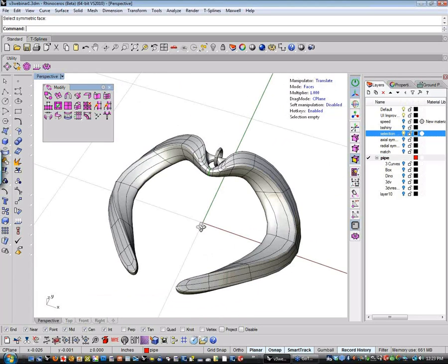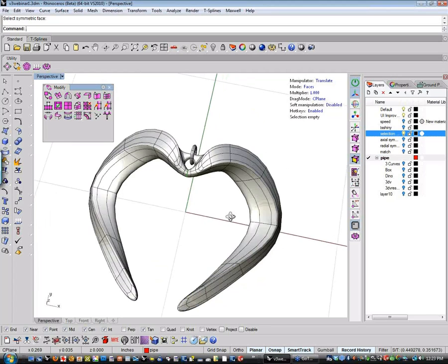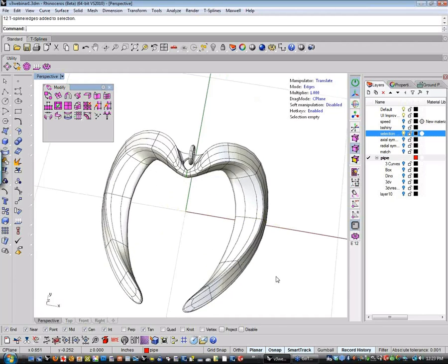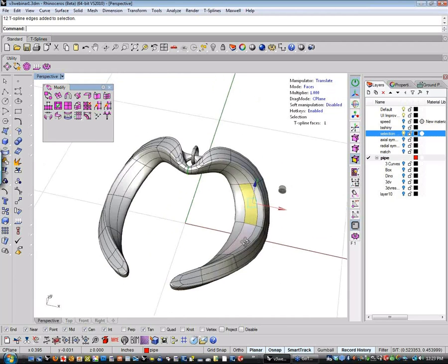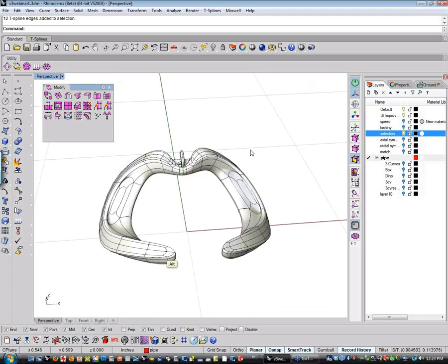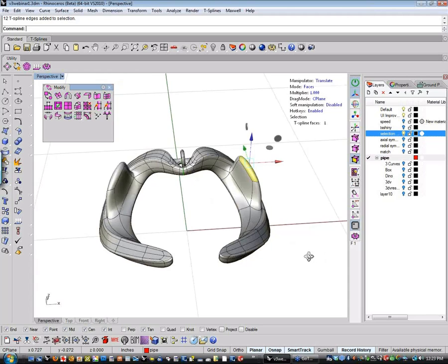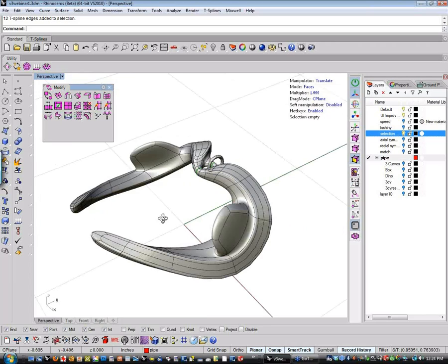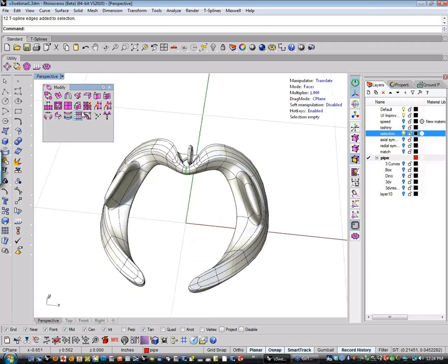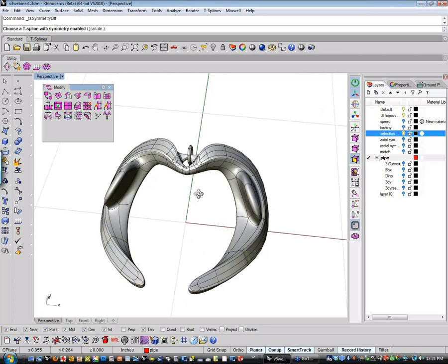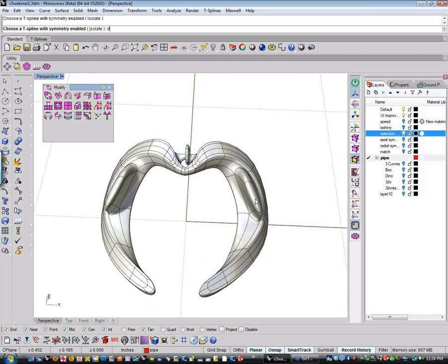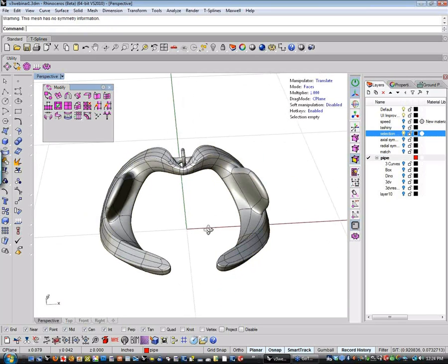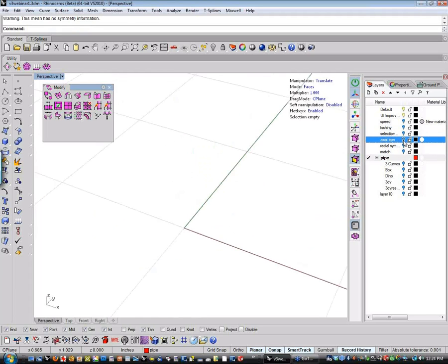But so that's really cool, and once this is activated, obviously you can come in here and pick any of this stuff and move it around, and it works symmetrically. It even works if you're extruding stuff. So if I put an extrusion in here, you'll notice that it extrudes it symmetrically across based on that once it's active. To get rid of it, all you do is right-click on this, pick this, and right-click again to accept, and now symmetry's gone, and I can modify this without having an update. So that's kind of the axial.